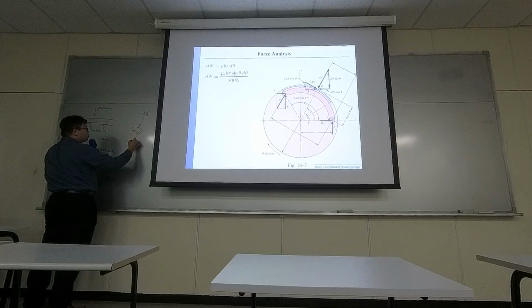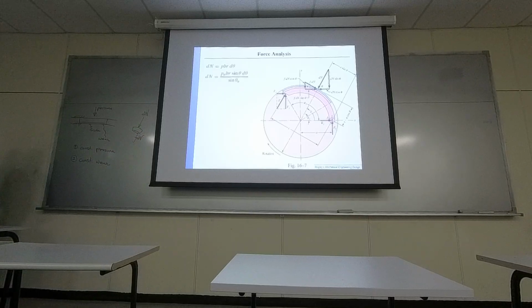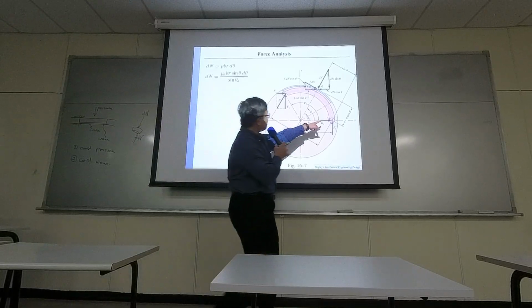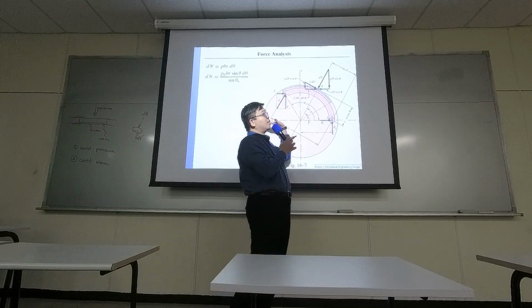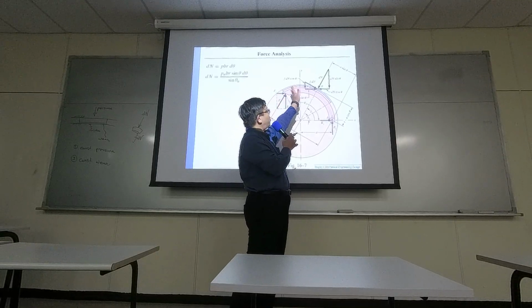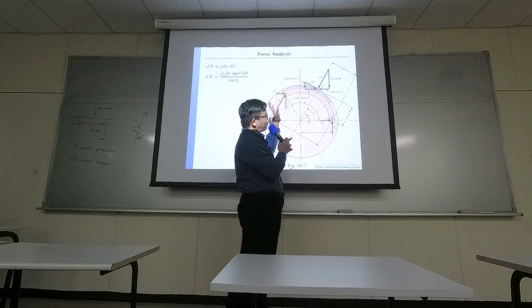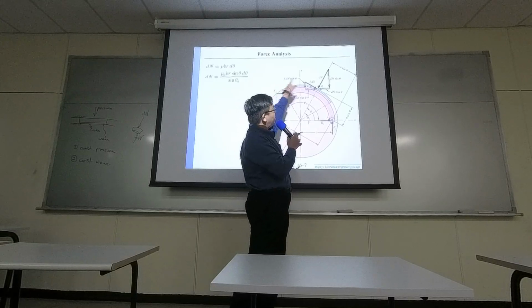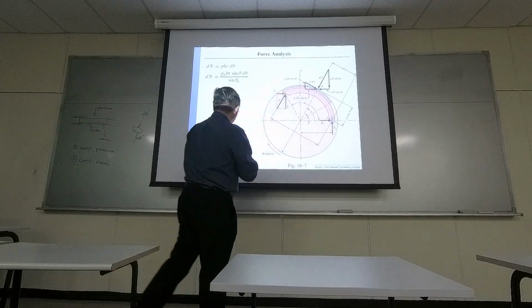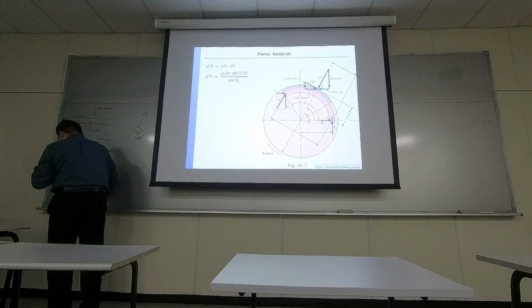So the friction force will be equal to the friction coefficient times the normal force. Okay, and then you will have reaction forces at point A, and you have an applied force. So you have a geometry, a mechanism that drives a force. You have a driving force that pushes your clutch toward the inner ring. So you want to solve for this force balance.